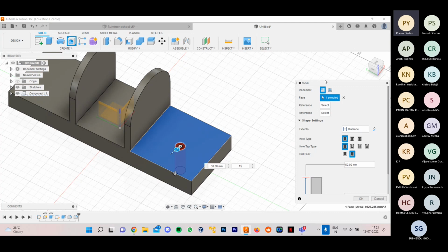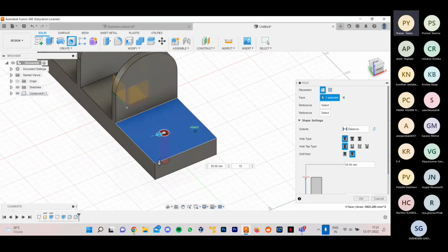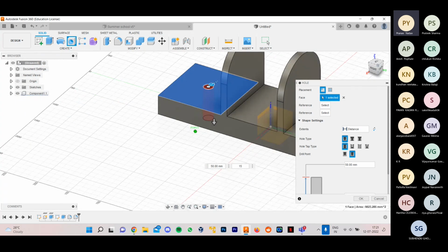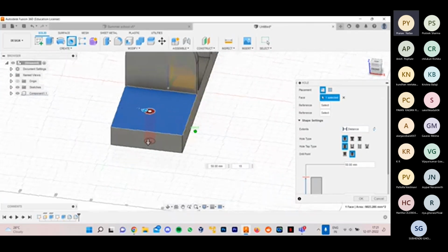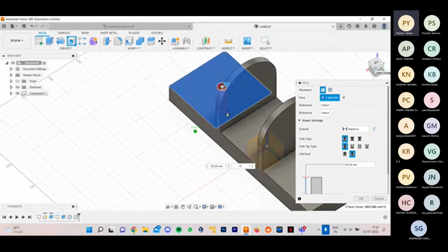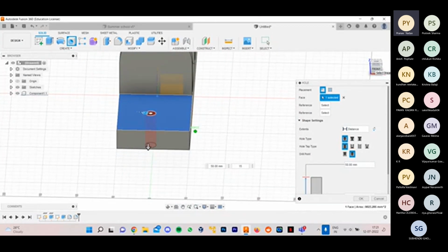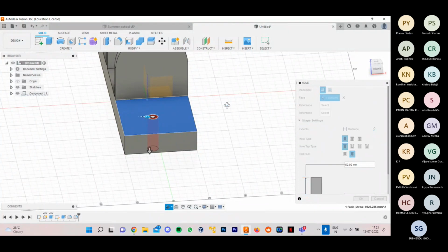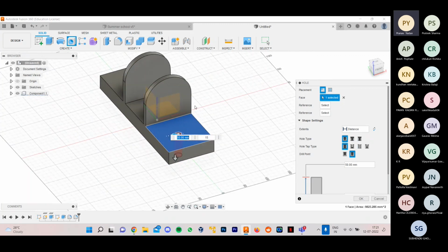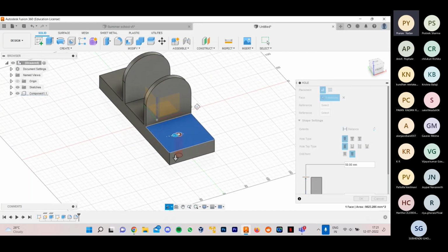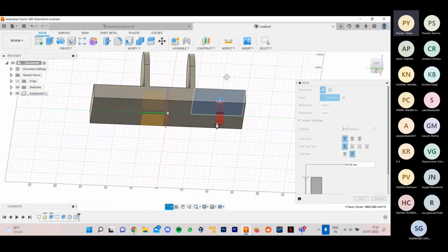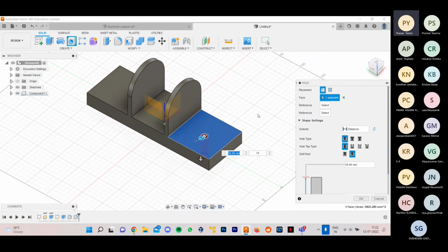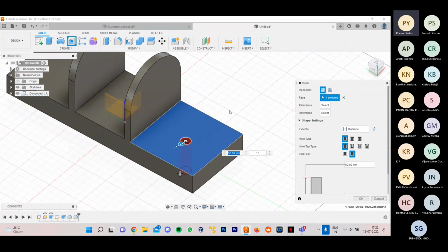So yeah. Also, one important thing, we have something at the top right. I don't know what we call that, but it's actually a good representation of the space we are in. If you touch that cube and drag it the way you like, it will actually orbit around the product that you want. But there's actually another way to orbit as well. Just press the shift key and click the middle mouse button to orbit. Just place your cursor anywhere, press shift and click the middle mouse button to orbit the product and see from different perspectives.